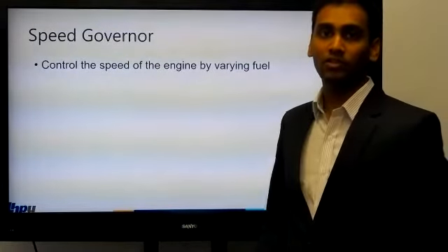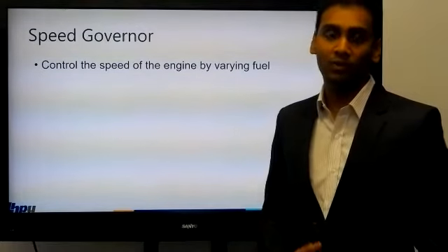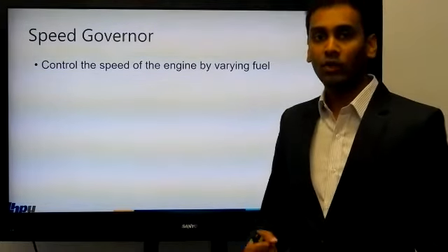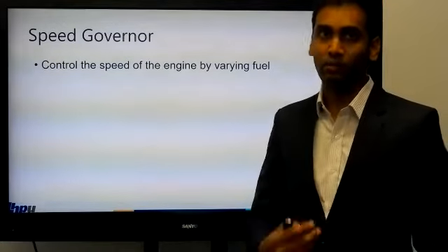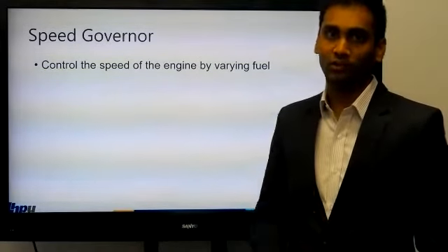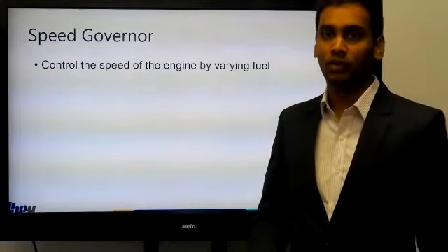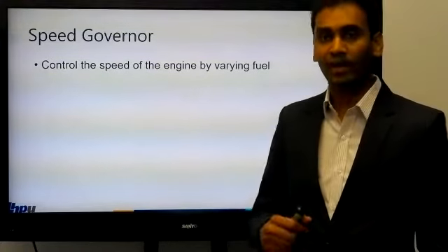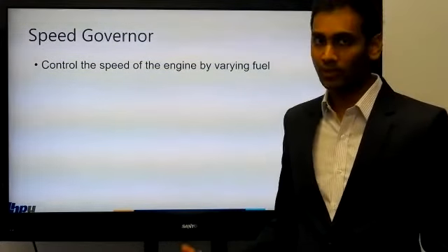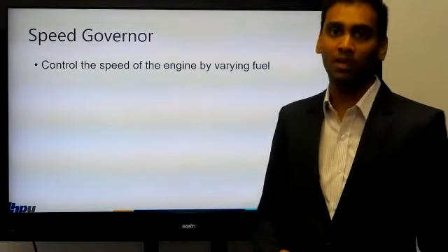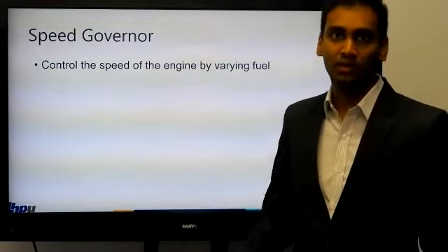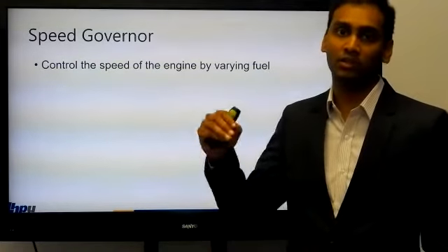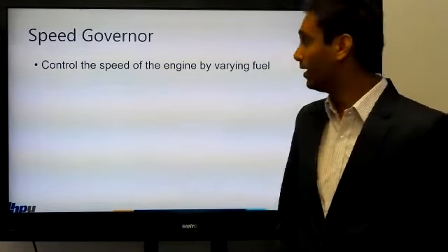Speed governors are the ones you find in your vehicle once you start it. You can also find that your engine is idling at a certain RPM on your tachometer once you start the engine. And your engine is also limited to a certain maximum speed. Even that is done by the speed governor. In this case, we have 2 governors, the minimum and the maximum. The minimum takes care of the engine idling part. The maximum takes care of limiting the engine to the maximum speed.